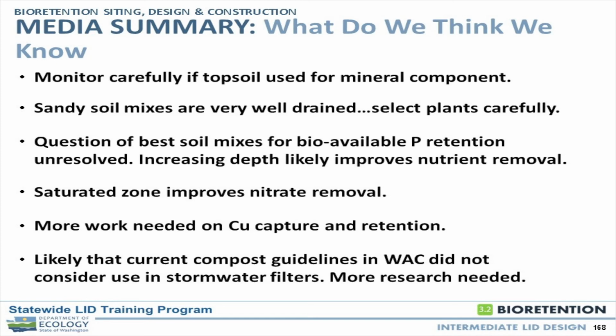Nitrogen gas is given off, and it will speed up global warming and climate change dramatically. No, I'm just kidding. I don't know how much nitrogen comes out of bioretention areas, but at any rate, you convert nitrate to nitrogen gas and can significantly reduce nitrogen levels. That's good news. We still need more work on the copper capture, but we've got some materials that are working pretty well. Again, phosphorus is really unresolved. It's the toughest problem we face with bioretention right now.